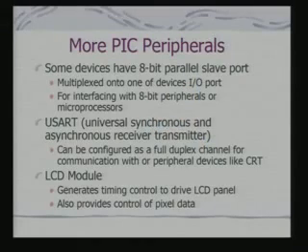In fact, the example that I had already shown you, the clock, that means a real time clock, you can implement by picking up a simple PIC, interfacing an LCD module and putting in a crystal, and obviously by writing appropriate software and loading it onto the PIC. You really do not need any other components.